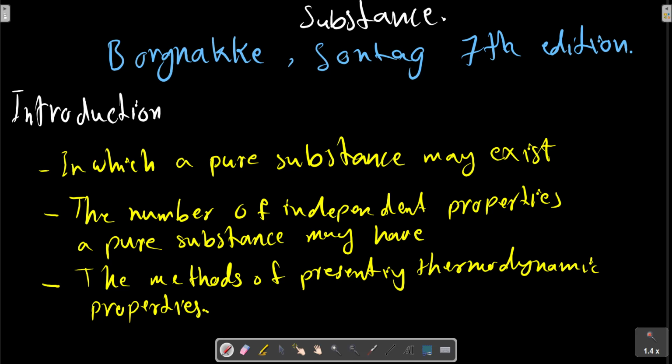Properties and the behavior of substances are very important for our study of devices and thermodynamic systems. The steam power plant and the nuclear propulsion system have very similar processes, using water as the working substance. Water vapor is made by boiling at high pressure in the steam generator, followed by expansion in the turbine to a lower pressure, cooling in the condenser, and return to the boiler by a pump that raises the pressure. We must know the properties of water properly.